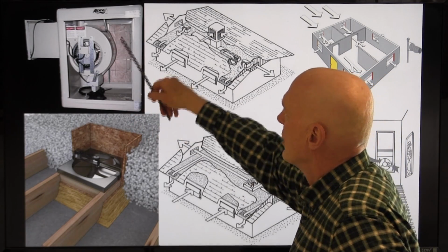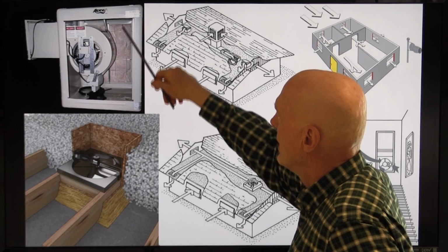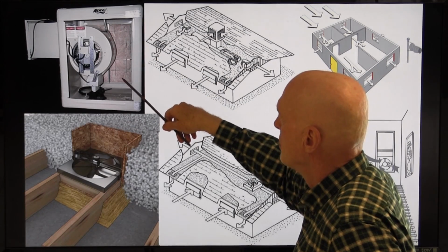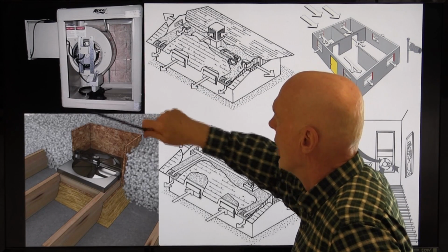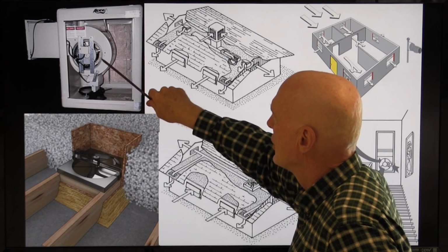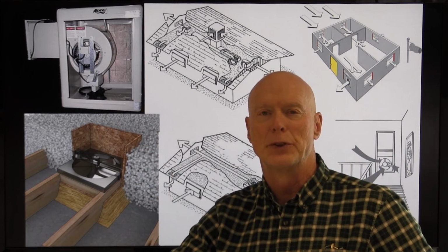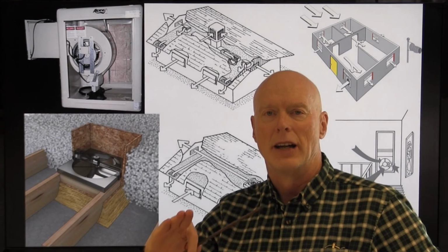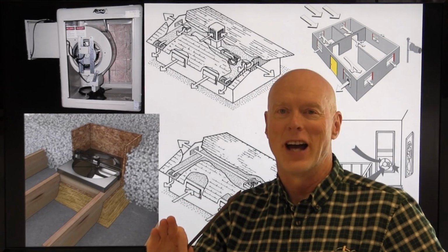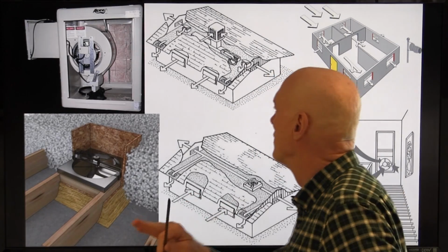And this surface right here is a pad, and you have water dripping onto this pad, and you have this blower sucking air from the outside into here, humidifying the air, which drops its temperature. Now, this is for dry climates. It doesn't work in wet climates.